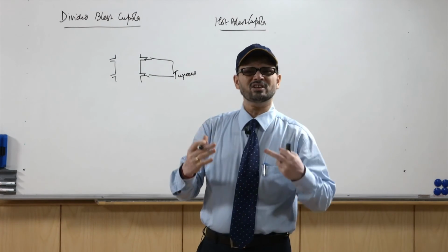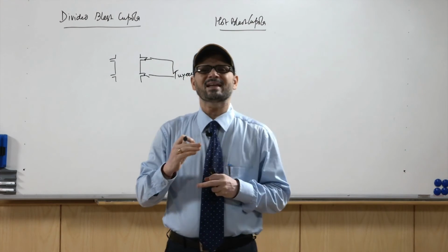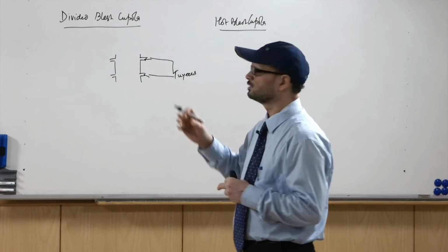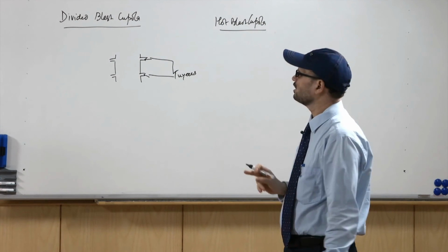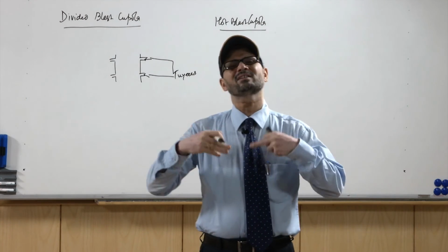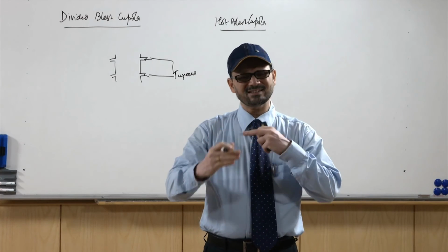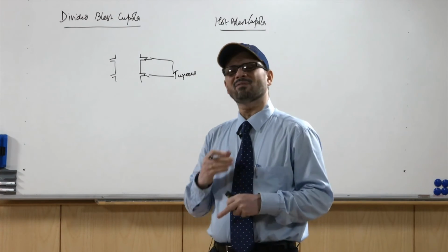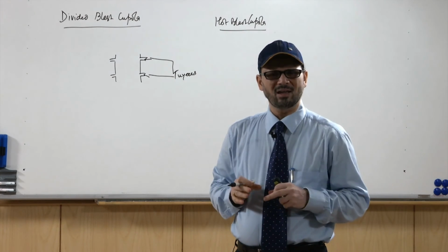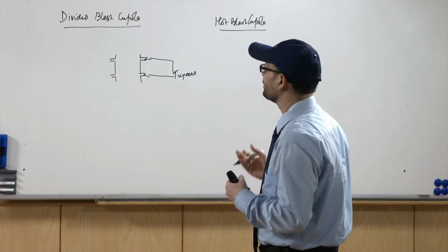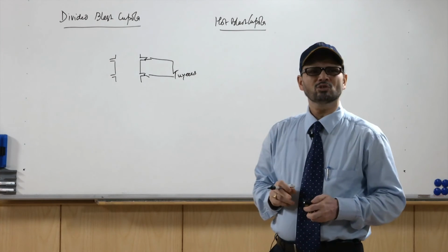The temperature of the liquid metal can be found a little bit higher, maybe 50 to 100 degrees centigrade. So, that is known as hot blast cupola. So, you have different kinds of cupolas; these are basically the advancements in cupola. Similarly, the use of oxygen in the cupola is also one of the advancements in the design of cupolas.